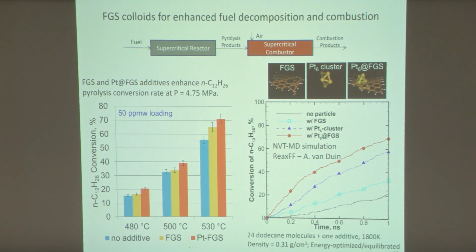And so one proposal has been to put structural catalysts on the fuel lines. Then as I pass the hydrocarbon fuel through those fuel lines, the catalyst will start to decompose the hydrocarbon fuel, and an endothermic process, breaking bonds, will occur, which will absorb the heat, which cools the fuselage or the engine. But the problem with that is over time, those structural catalysts start to become coated with carbon deposits.